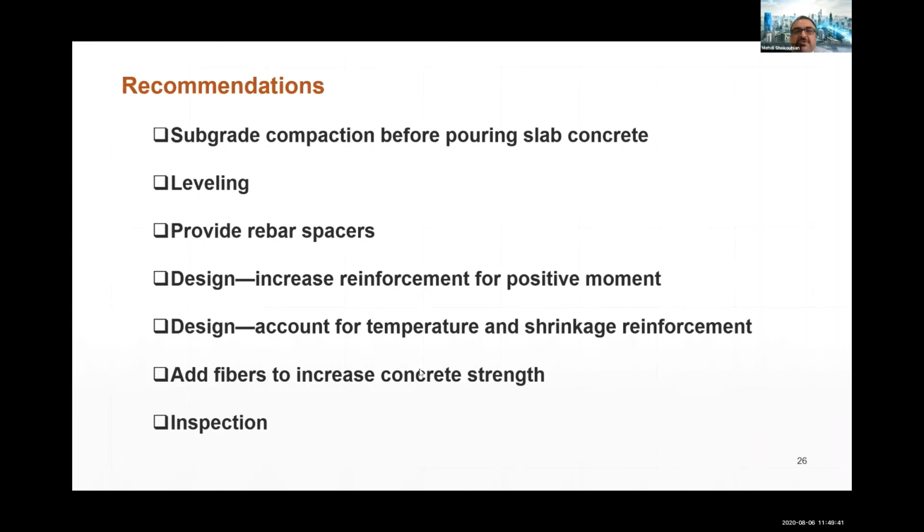And recently, one of our projects funded by Region 3 is using recycled steel fiber extracted from waste tires in the concrete to enhance the mechanical characteristics of the concrete bus pads, as well as having a positive environmental impact by using recycled material.